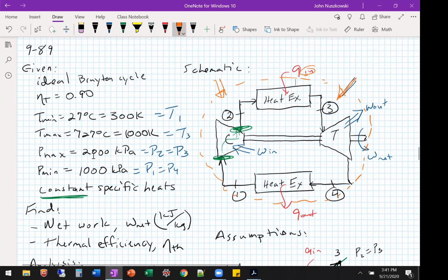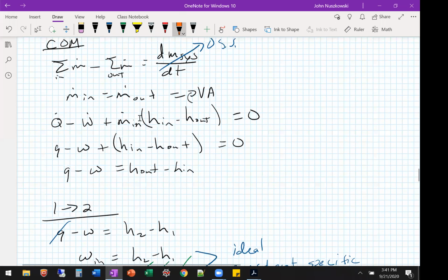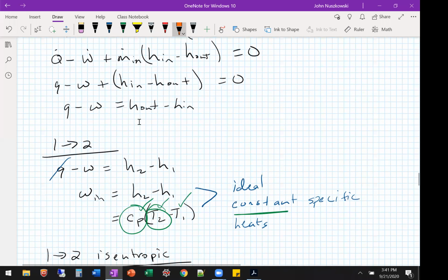So like we did for work in, we had enthalpy out, right, was H2. So this would have been negative work is H2 minus H1. But I changed that subscript to work in, which gives me H2 minus H1 without the negative, because that basically that in tells us the direction of the work.